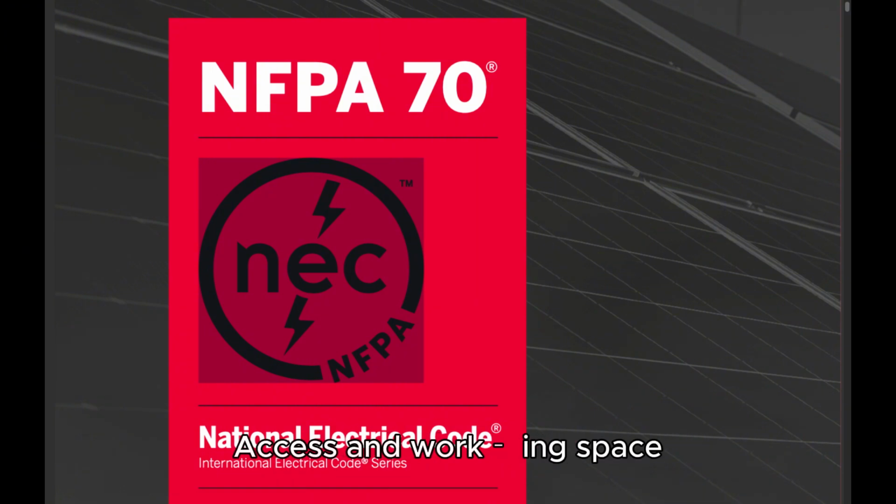Access and working space shall be provided and maintained about all electrical equipment to permit ready and safe operation and maintenance of such equipment. A working space for equipment operating at 1000 volts, nominal, or less to ground and likely to require examination, adjustment, servicing, or maintenance while energized shall comply with the dimensions of 110.26(A)(1), (A)(2), (A)(3), and (A)(4) or as required or permitted elsewhere in this Code.